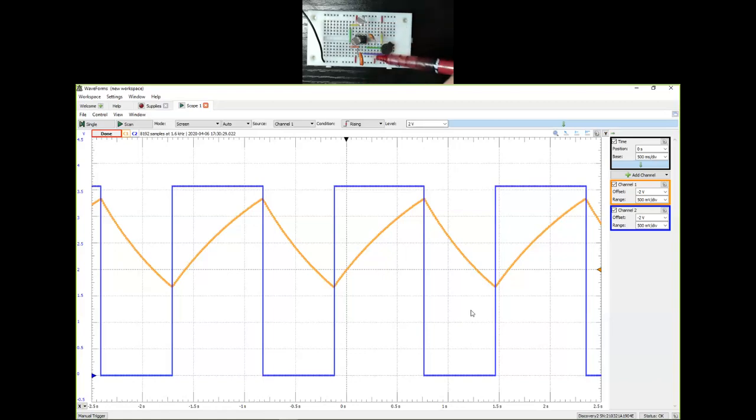And when I do that, I'm going to be generating a different frequency square wave, which now I'm going to try to hear using a buzzer that is shown over here. So compared to the previous circuits, just a few differences. R1 and R2 now are variable light dependent resistors, LDRs or photoresistors. Earlier we had fixed resistors, and we have changed the output from LED to a buzzer.